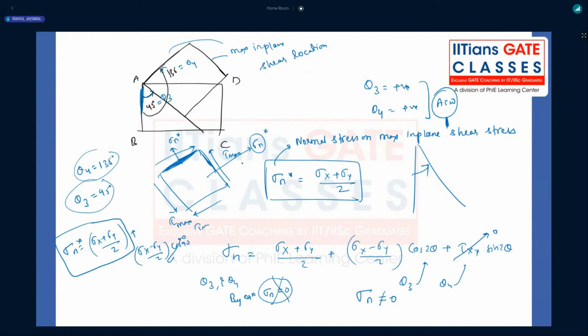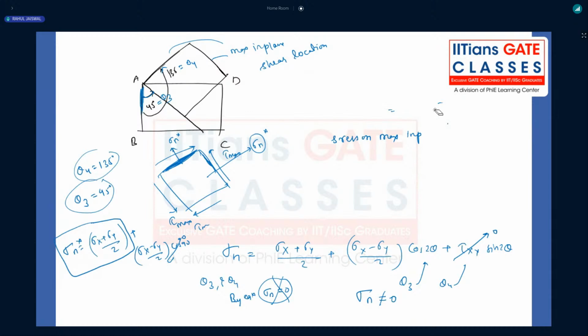Tell me, guys. With the help of Mohr's circle, things will be more clarified. But as of now, whether these things are clear or not, tell me. Now some of you might be asking, sir, please derive that. I'm not getting the clarity of why exactly we are getting sigma n star. You got the value 45 degrees, from that basis you are telling, but analytically by putting into the formulas, why are we getting sigma n star, that it has to be 0? No. On a maximum shear stress plane, normal stress need not be 0, right? If it is 0, that is a pure shear plane.